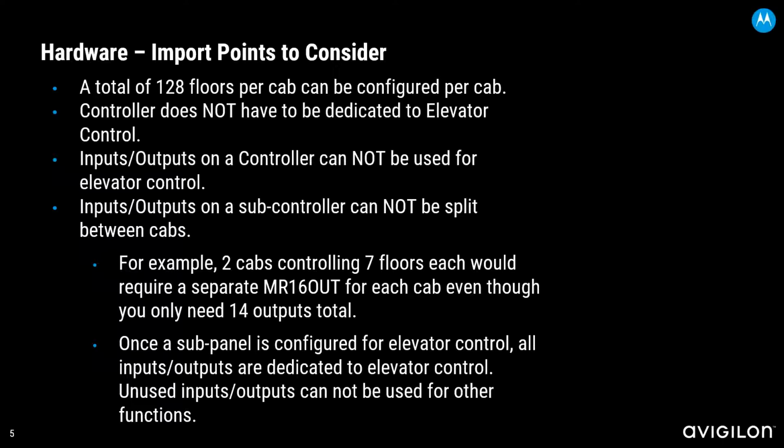Now, as I mentioned before, the controller does not have to be dedicated to elevator control, but you may want to do that just because of the physical layout of the building. Maybe you want some fault tolerance. We have had some people that will do a separate controller for each cab. They don't want a controller failure to take down the entire bank of elevators. All those are legitimate strategies.